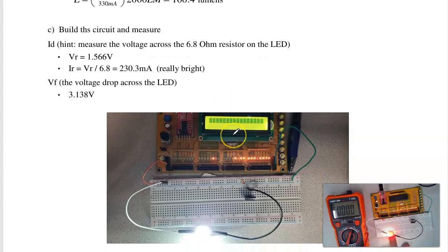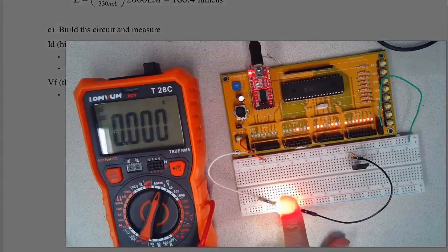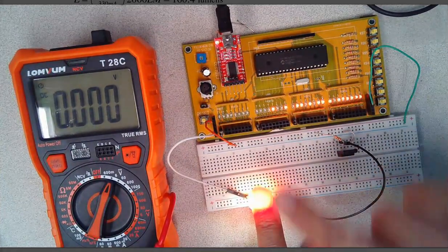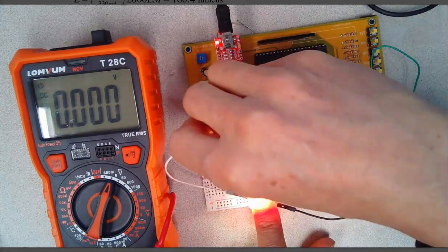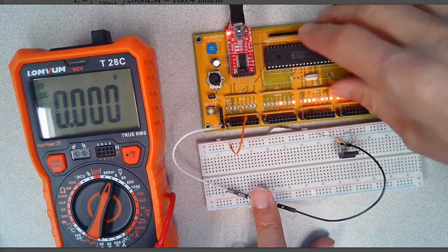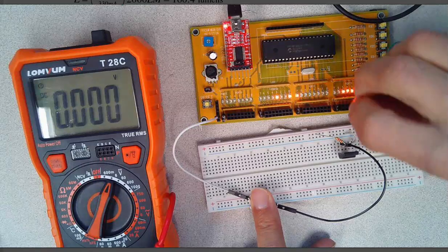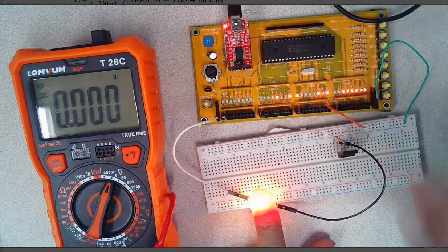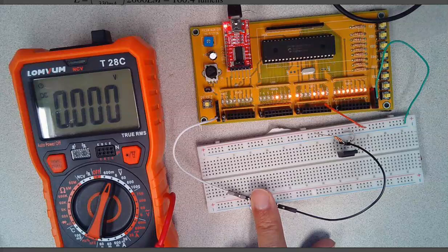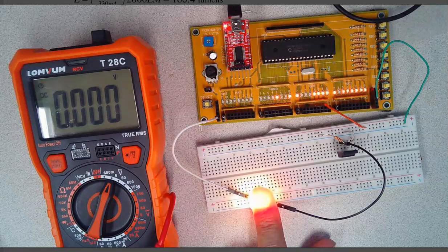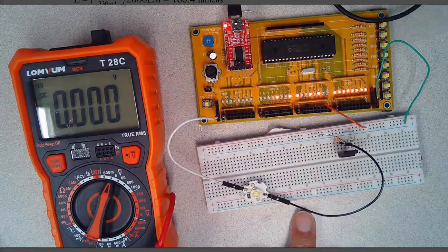And I wind up with the PIC able to turn the transistor on and off. So here the base is tied straight to 5 volts. If instead I tie the base to a pin from the PIC, like right here, you can see the LED turning on and off. I've got my finger over it to dim it.